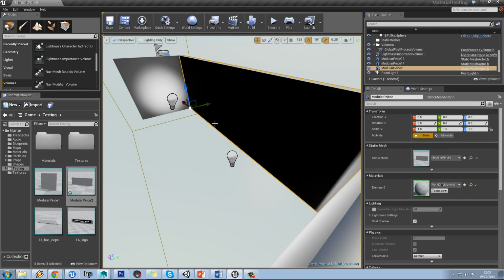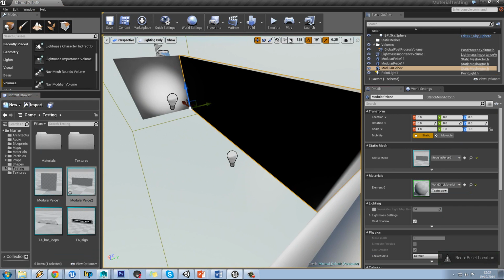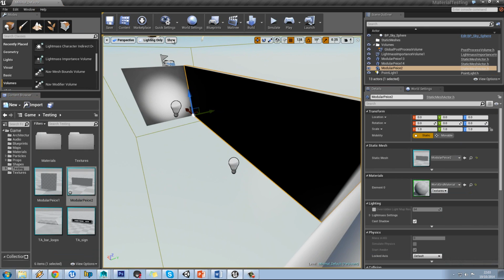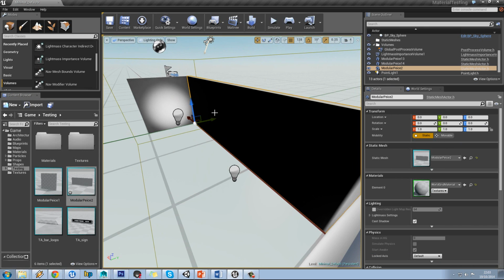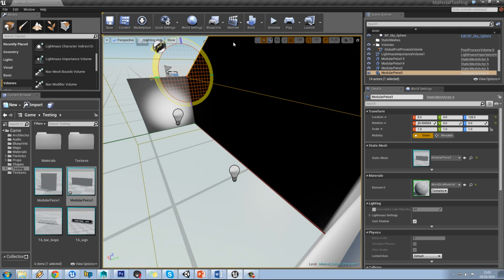We'll just follow exactly the same process we did before. We'll clone that up, turn on our grid snap and make our grid visible. Hold Alt, snap that and rotate it.